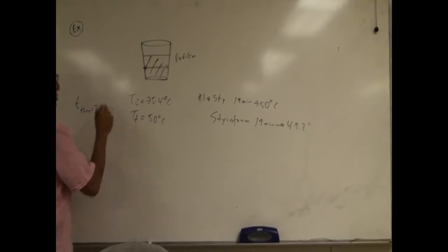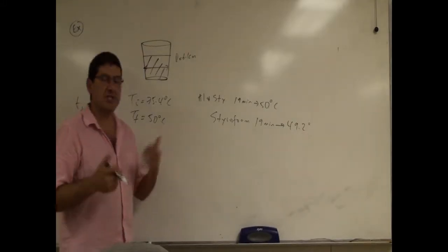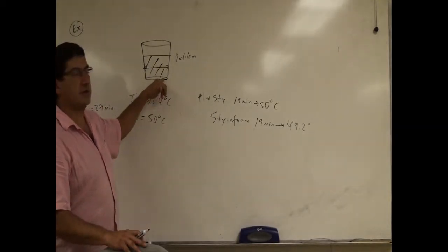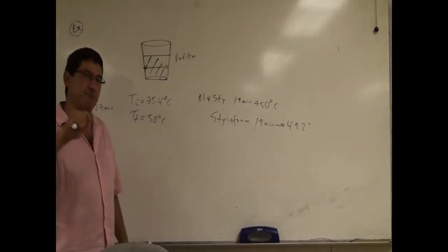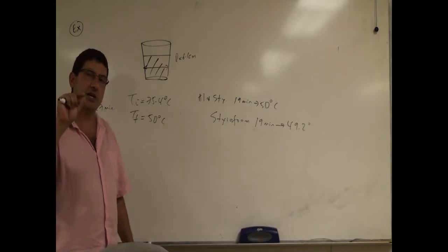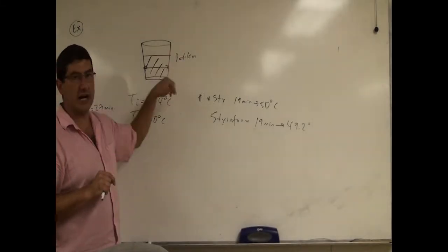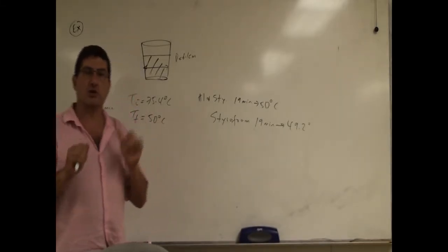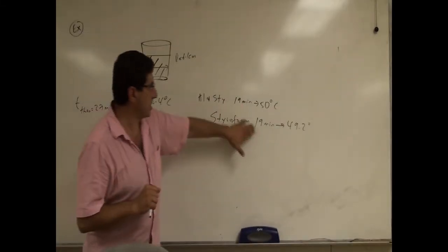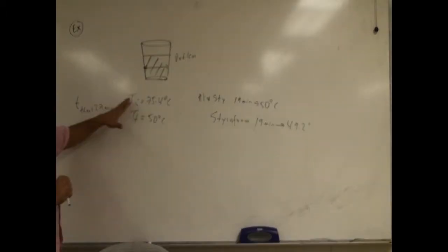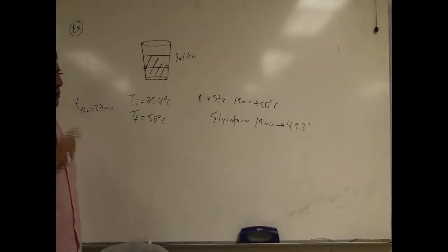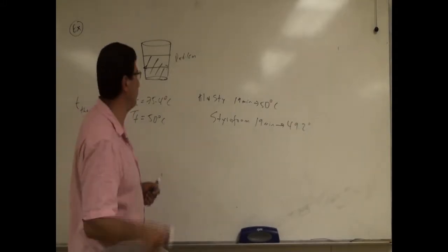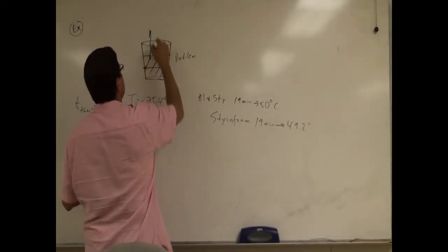27 minutes. So that got me thinking, what were some of the primary sources of error? Well, one of them I had mentioned in the video: the thickness of the bottom portion of the cup was thinner than the sides, so we had assumed that the bottom is also the same thickness. So that's going to cause both of these to cool quicker than the theoretical result. But also primarily we had ignored the radiation of heat through the top.